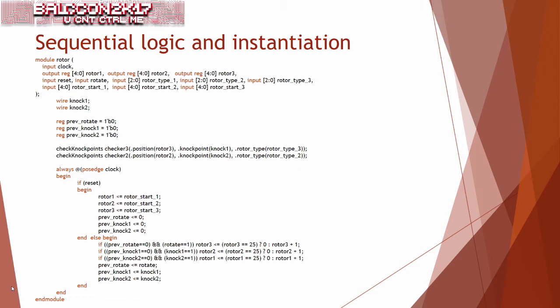Also, you have the variables, like you have in C. You will have vars. So var is a variable, which you just keep temporarily, and the register is something that you wish to keep for the next run. So you can put initial state for it, so that is how it will be initialized. And here is instantiation. Instantiation is basically you put the name of the module in which you have defined it. You put the name, how you will call that instance, and then you propagate parameters by name.